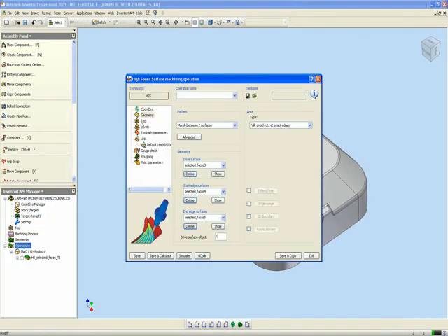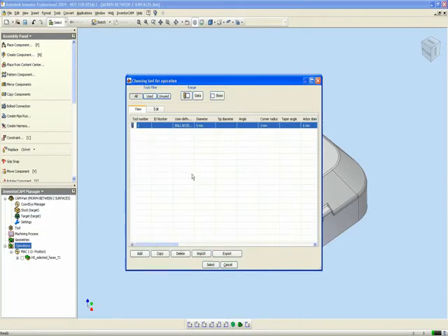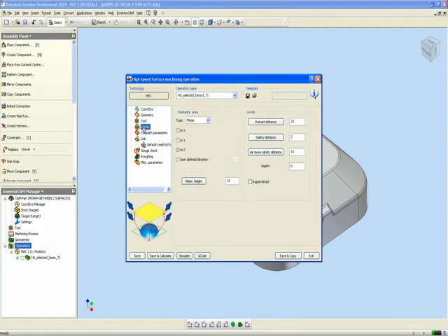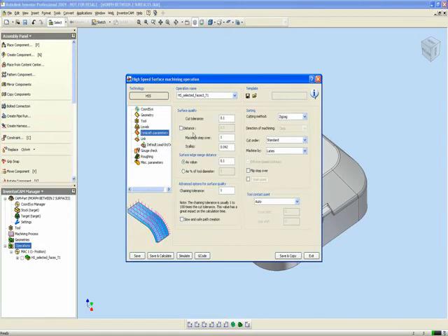The tool that I'll be using will be a 6mm ball end mill. My levels, I'll leave them at the default values they are right now. My toolpath parameters, I'll choose a maximum step over of say 0.5 millimeters, and I'll be working zigzag back and forth.